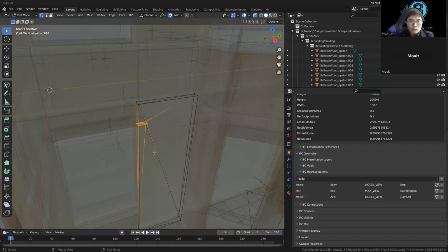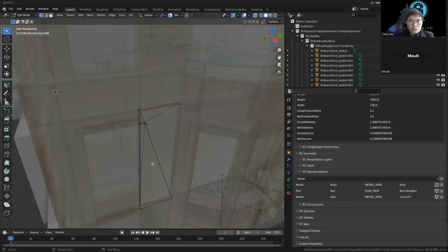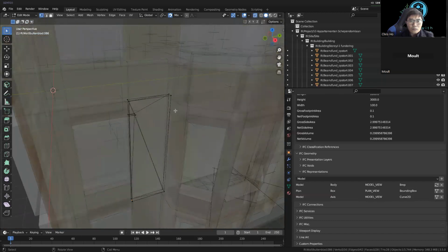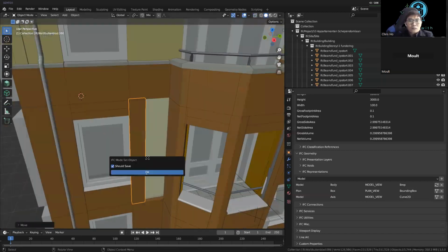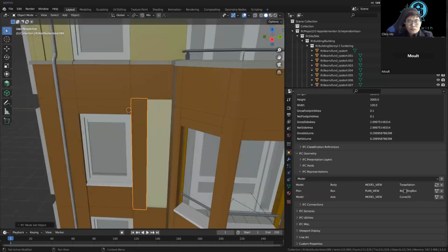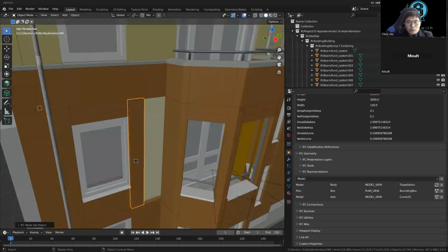In this case, it's no problem for me if I want to edit this wall. If I wanted to stretch out that wall in a particular direction, no problem. I'm done. I've just updated that BREP. It's upgraded to a compatible type of tessellation for IFC4, and I've just edited that wall. You can see that was very simple to do. However, it may not always be that simple.